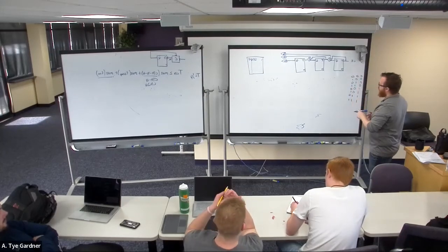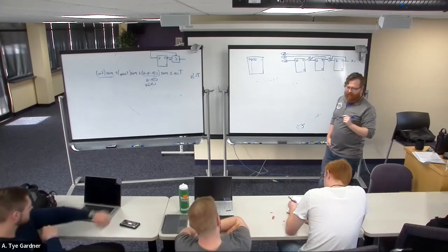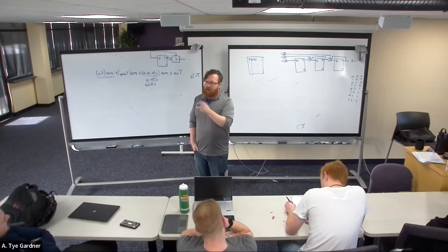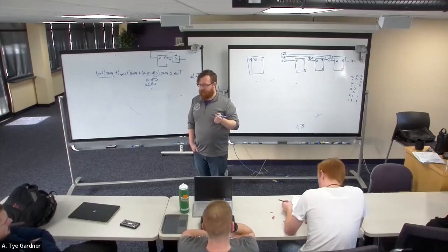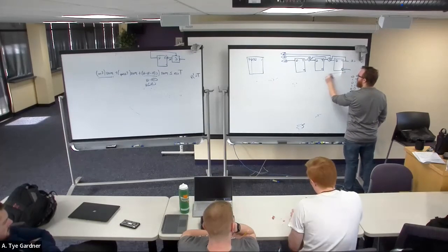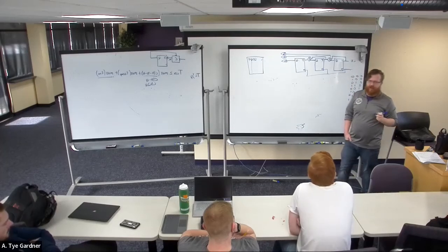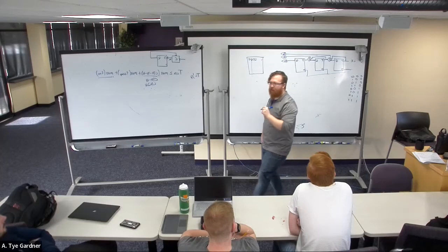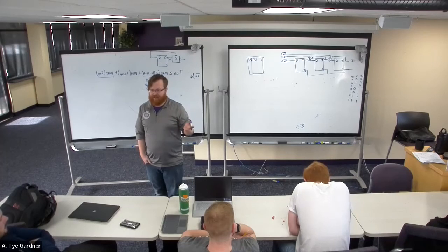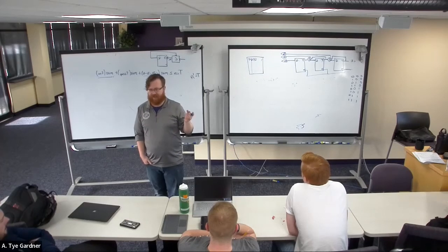And the other one, this actually has 2 purposes, because this isn't only a counter. Well, it is, but we can use a counter in a different kind of clever way. So to that point, if you were to hook this up to your FPGA and hook your clock in to these devices, would you see the LEDs counting? No. Why? Too fast. It's too fast, because the clock on your FPGA is 100 megahertz, which is way too fast for the eye to have any hope of seeing, 100 million times a second. No, your eye's not going to see that.